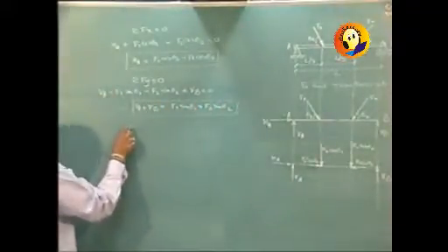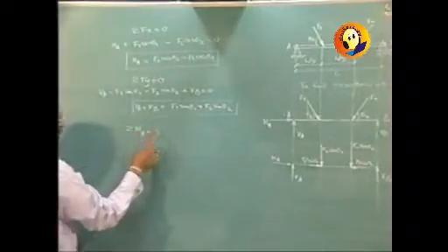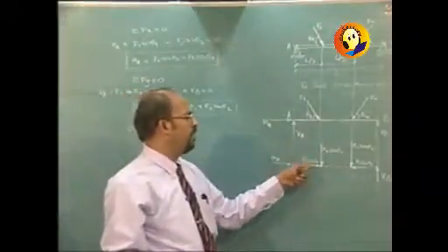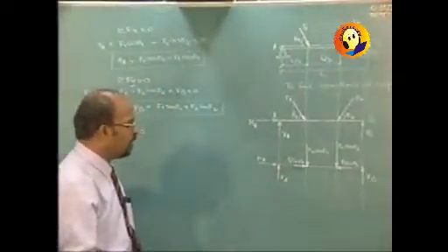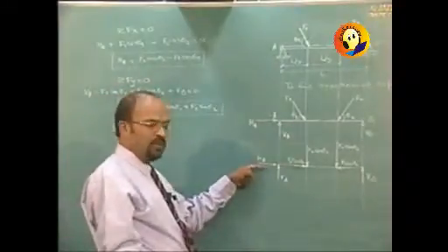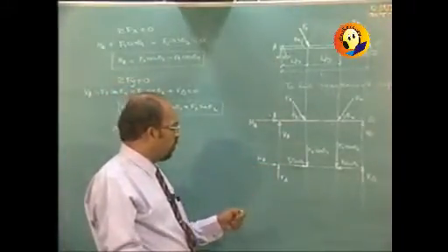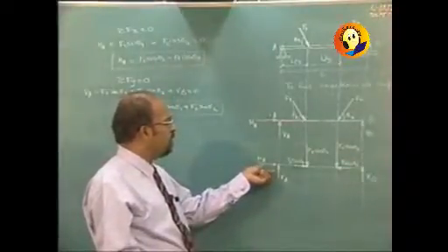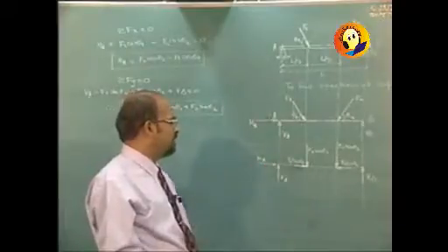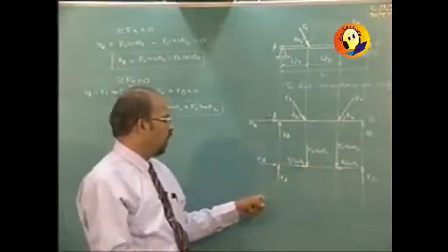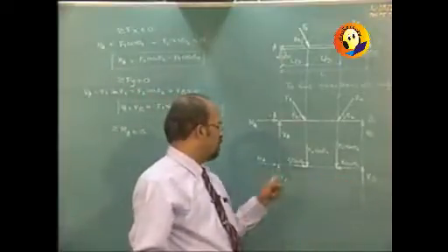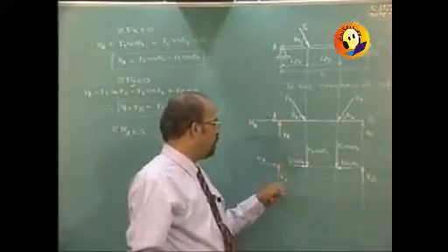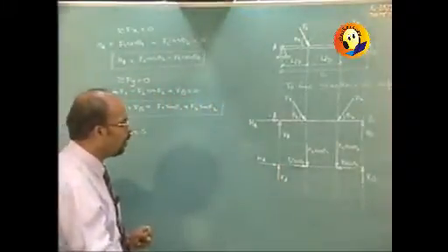And then sigma moment about A. Up till now I have been taking the moment about A. Actually it could be any point on this particular beam about which you can take the moment. The criteria for choosing the point at which we want to take the moment, from our calculation point of view, we will say that it should be the point at which the maximum unknowns are intersecting each other, like HA and VA and VB. Out of that, VA and VB are not intersecting. So HA and VA are passing through a single point A. So we should be taking the moment about point A only.